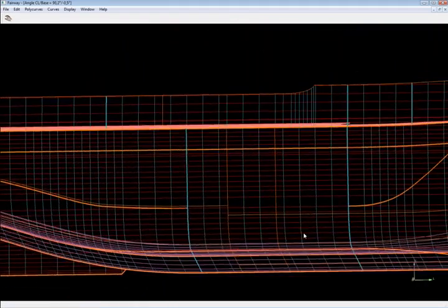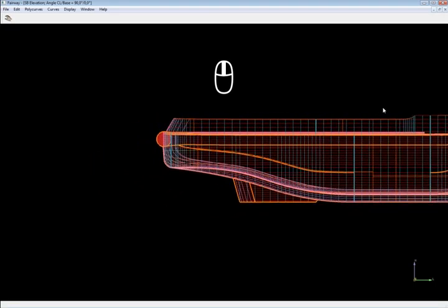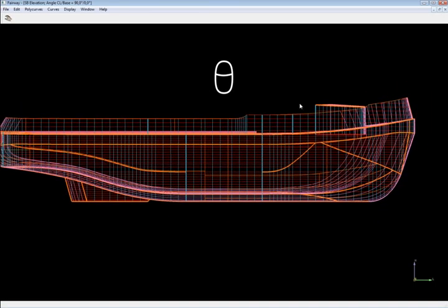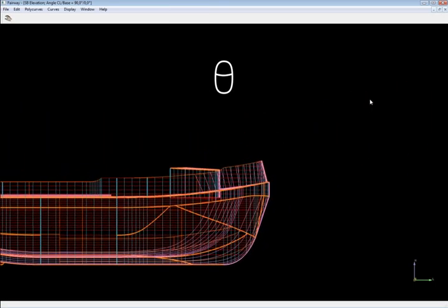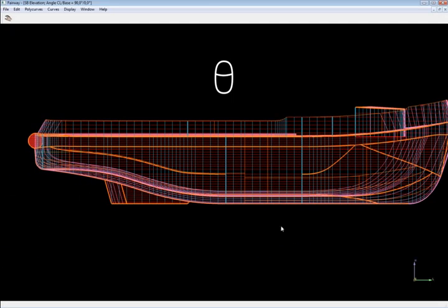Panning can be done in two basic ways. First, you can simply press and hold the middle mouse button, then drag the drawing sideways. Secondly, you can just click anywhere on the screen with the middle mouse button, and that point will slide to the middle of the screen on its own.